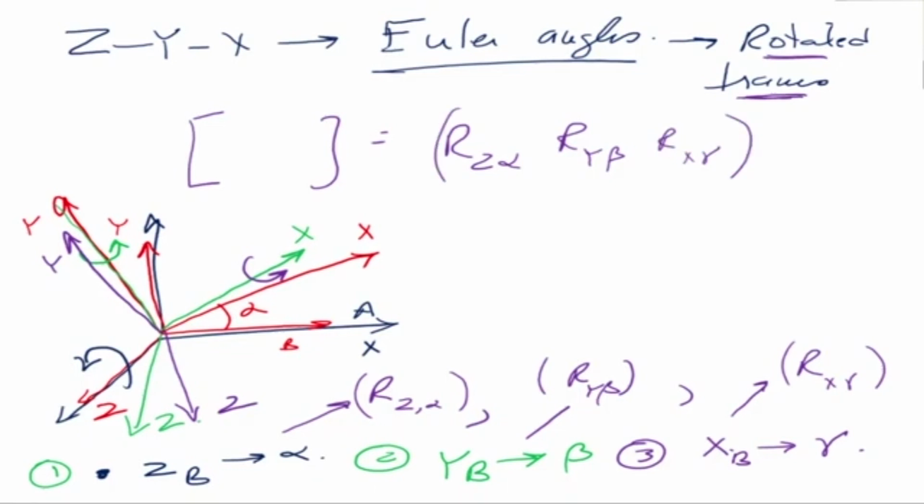Okay. So whatever was the order of rotation, first, second, third, that order does not change and it remains the same. So this into this into this. Please note that Euler angle rotations will change the way we are rotating, because we are rotating about the rotated system, rotated frame rather. What will happen is the matrices will not change. We will not pre-multiply the matrices. The order will remain the same.